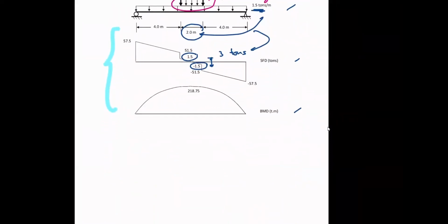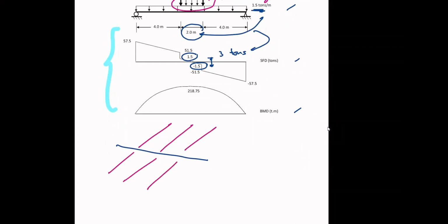When I have the main beam that supports secondary beams coming in like this, they generally come in from both sides. But I always calculated the load based on just one side. So instead of having the reaction from this beam, and this beam, and this beam, I had the reaction from one side only. So I missed the load by 50%, and when you miss the load by 50%, generally that means disaster.